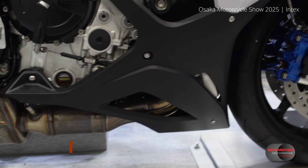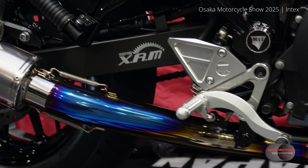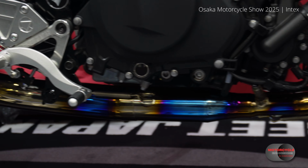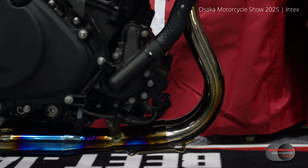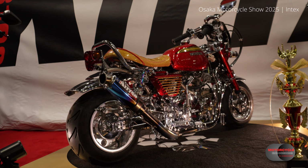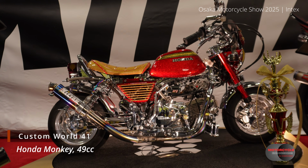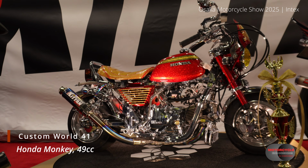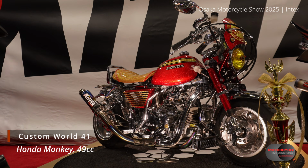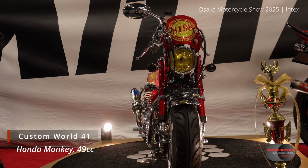So one key factor that influences friction loss is velocity. Usually if we have a fluid flowing down a pipe, we need to send a certain flow rate. Now if you have the same medium and you want to send the same volumetric flow down two different pipes, one larger and one smaller, it must travel down the smaller pipe at a higher velocity. Meaning that by using a smaller pipe, we're going to create excessive friction loss, which results in back pressure.